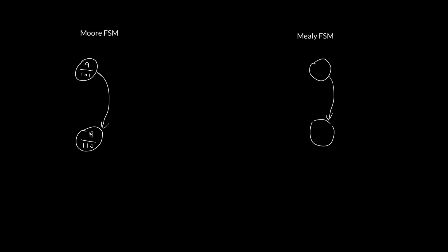And then this transition here tells me if I am currently in state A and I get a certain input, then I'm going to follow this transition. So I need to know how many different inputs we can have. If we have a 2-bit input, then I can label this transition 1, 0, meaning if my 2 bits of input are a 1 and a 0, I move along this transition here.